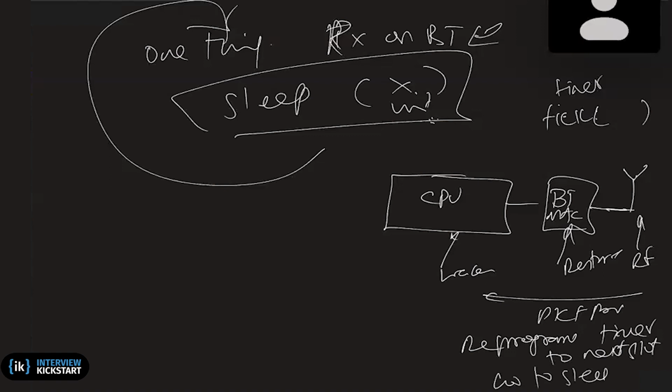This is one scenario. Here, what you are programming depends on the packet. For example, when you reprogram the timer, depending on the type of packet, you might have spent more time processing it. So the remaining time may be variable depending on the complexity of the packet processing. You will program a slightly different value, not a constant value. Right. But the next event is determined by the protocol. Yeah, exactly. So this event is pre-known, defined by the protocol, like an advertisement interval.